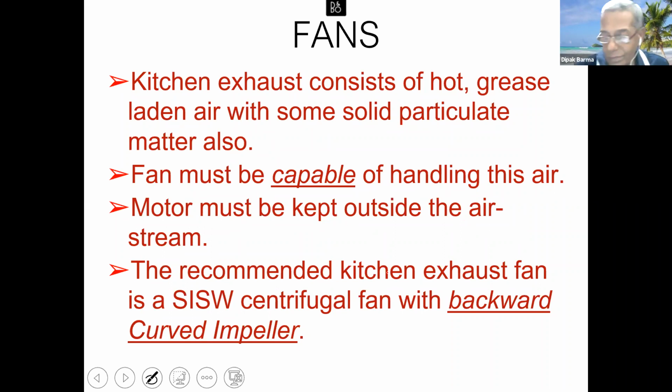Blowers for exhaust. I'm not talking about the blowers for the fresh air, because that's standard, normal air. You can use any blower. You could use a tube axial fan, but it's noisy. You could use a plug fan, whatever you feel like. There it's not an issue.